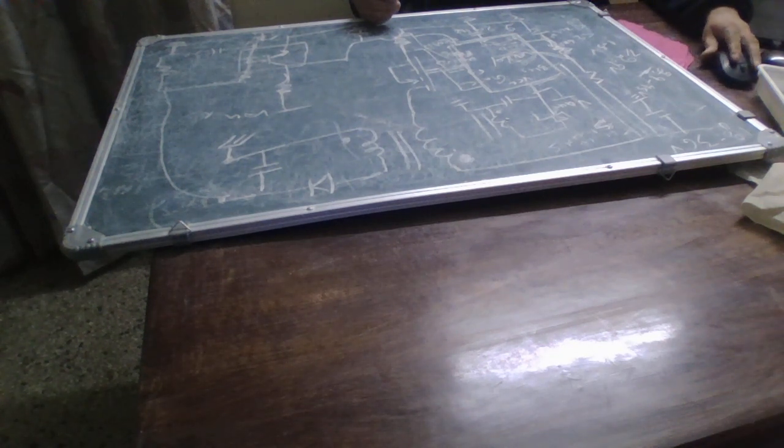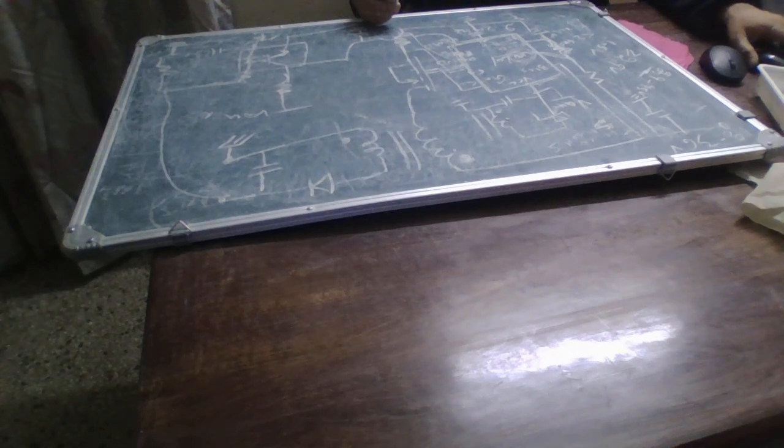It's the drain current connection of the internal N channel power MOSFET. And lastly we have an EP pin. I'm not going to use it, because that's an exposed pad of this package. The exposed pad must be connected to the AGND and the large ground copper plane to decrease the thermal resistance.